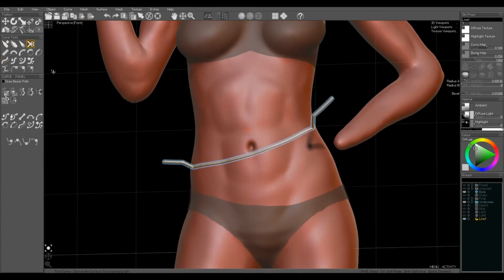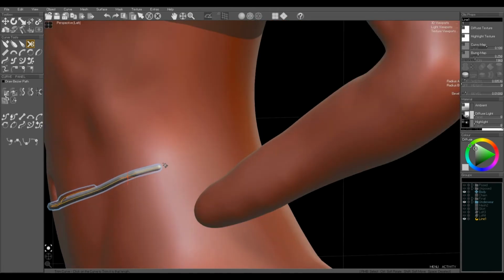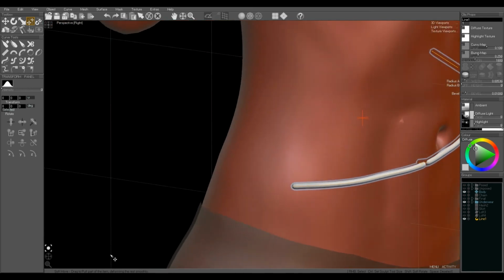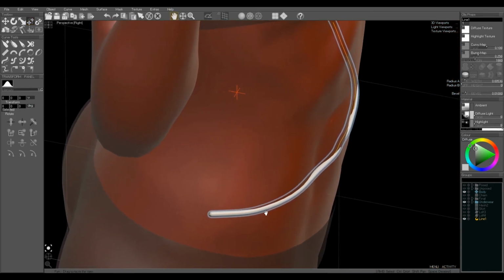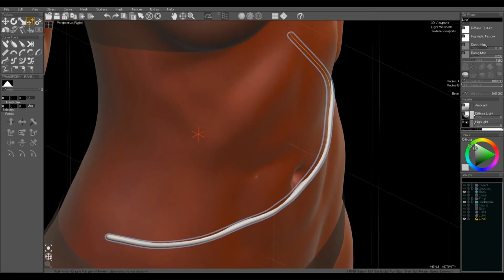And we have some scraggy ends, which we can trim off with the scissor tool. And now this line maps onto the body. It's not quite as long as we'd want going around the body, so I'm going to drag those out by hand. And just tweak the surface to match nicely.